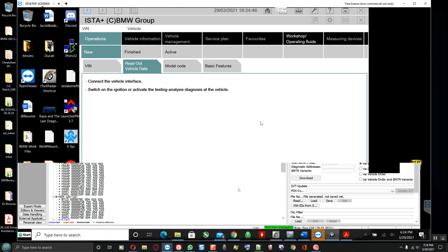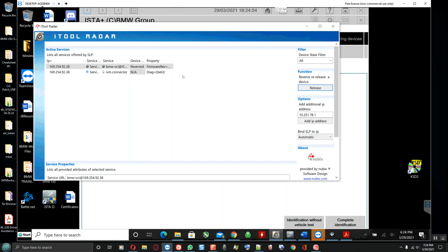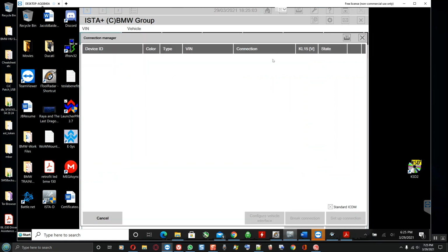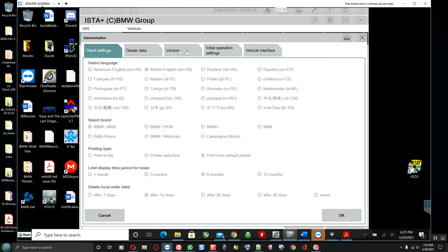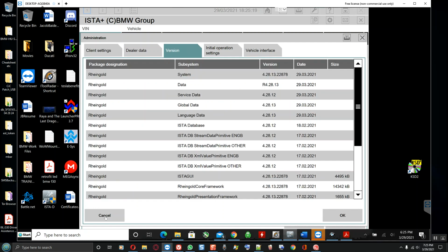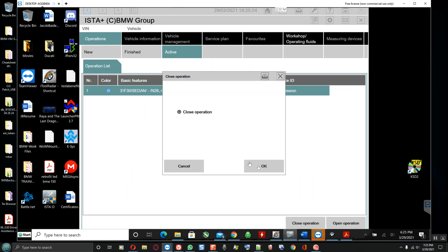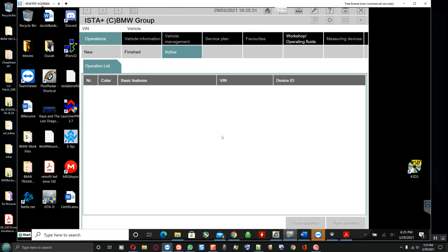Basically, when I hit that code default values, I remember originally it only had one CAFD underneath the module. And then when I did the code default values, there were three of them, with that 255, whatever. I mean, you know more than me, but I think those extra CAFD files that we had to add in to fix those default values are maybe screwing something up, because the fault that's in there I know wasn't in there prior to the coding stuff.